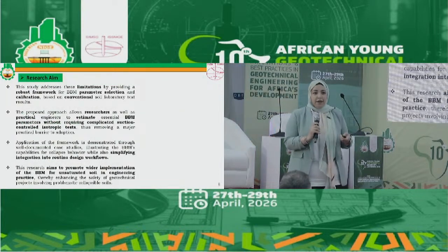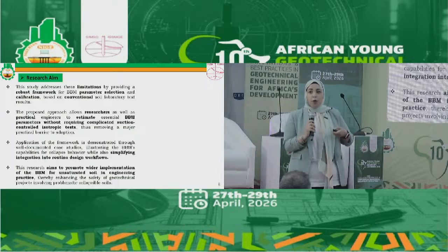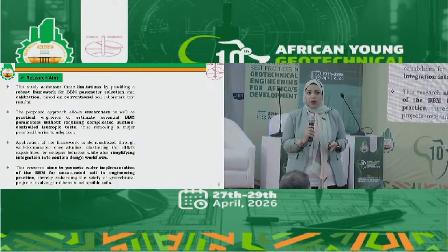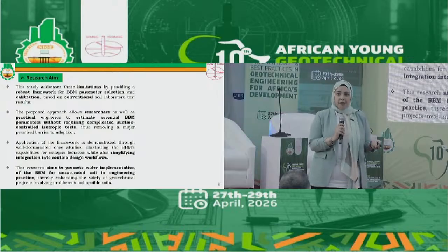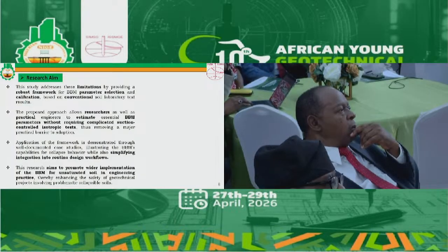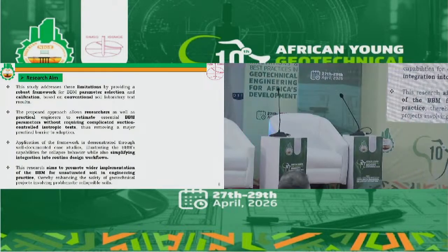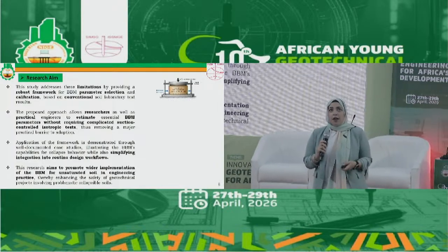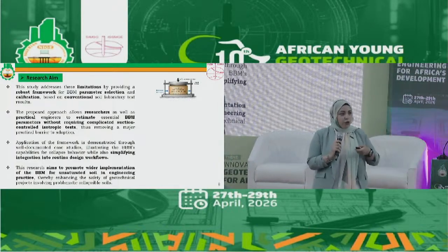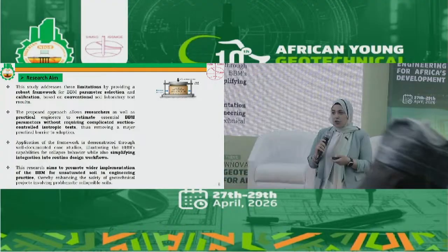However, this research aims to promote the use of the Barcelona Basic Model in practical engineering. My aim is not only for research, I want practical engineers as well to be able to use the Barcelona Basic Model so they can study the effect of collapsible soil and prevent failure. The main idea, I'm not going to go too deep, and if anyone wants more information, I'm available afterwards.